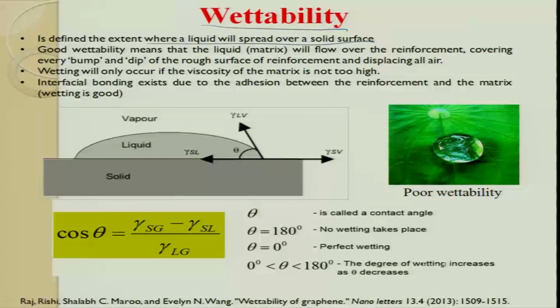This is wettability. You would have seen wettability in the lotus leaf. This idea is mimicked in a lot of engineering applications today to avoid corrosion. In metal matrix composites, they make very small textures on the surface, and then the water droplet does not stick to the surface.